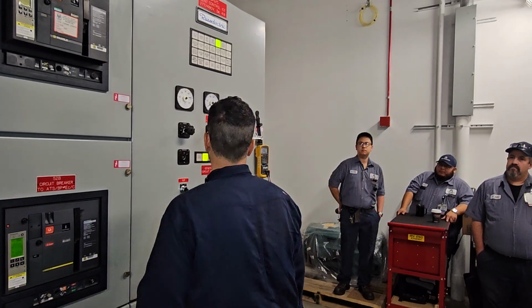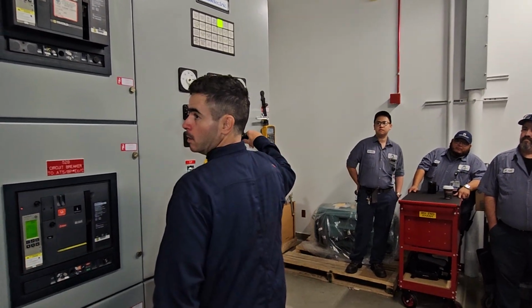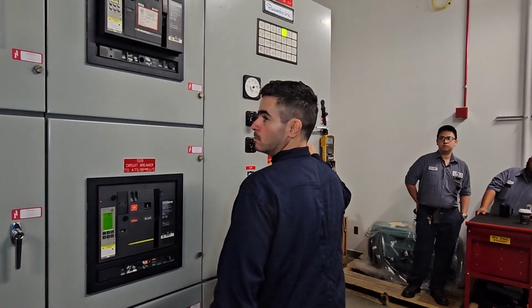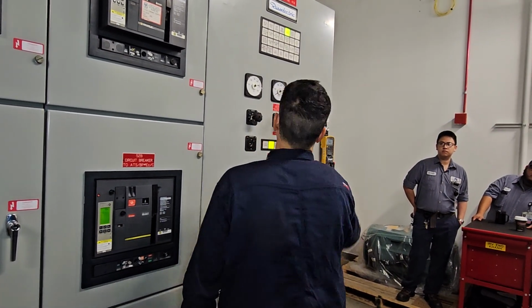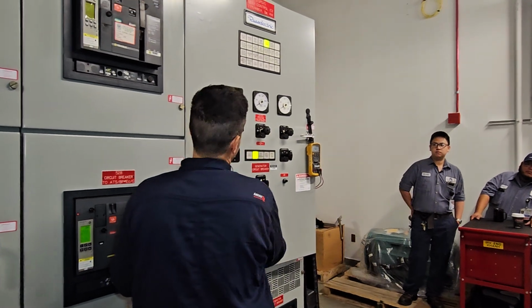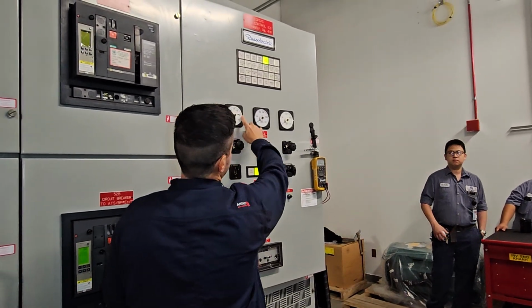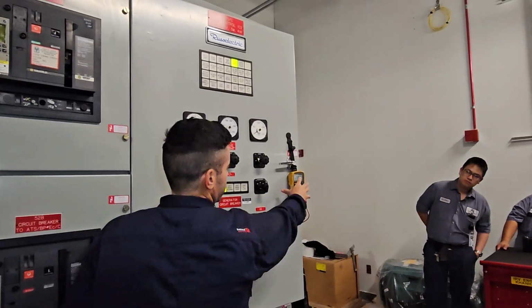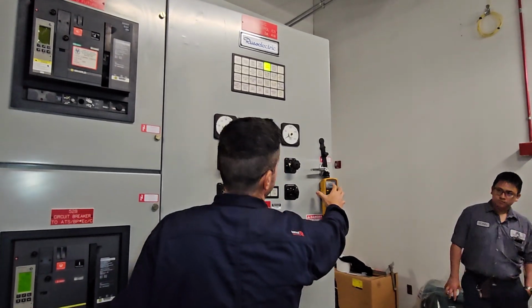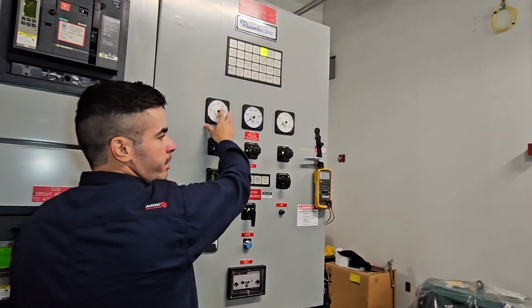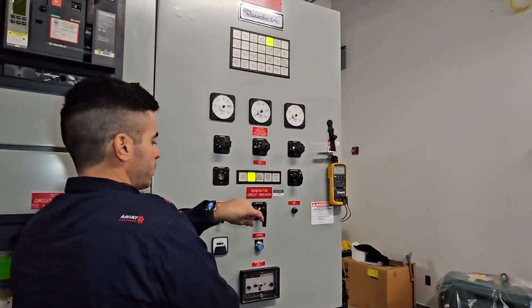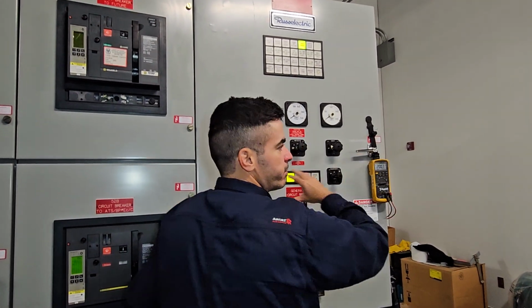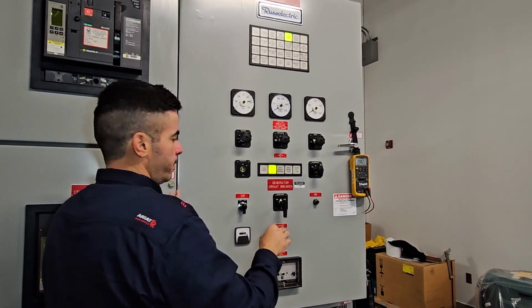Yeah, it seems like we have a problem with that frequency meter. It should be showing 60. All right, I'm going to exercise this so you guys can see how the voltage is actually increasing here and also here. This is the reason I see 200 volts here and 480 over here. This is the real voltage, but this is just my reference voltage after the PTs for instrumentation.